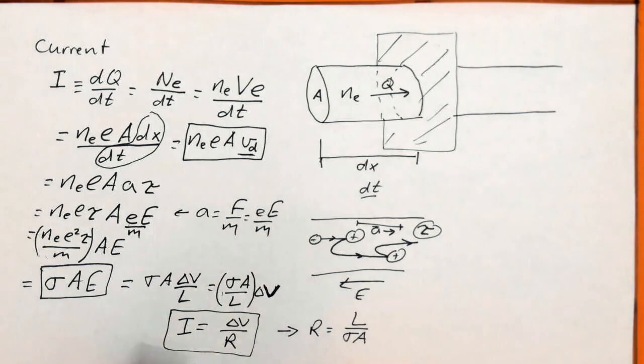And since sigma is conductivity, it's how well the material conducts. Since we're trying to talk about how much the object resists flow, we choose another parameter, which is simply 1 over sigma. So it really isn't anything new. It's just, if this is 10, then rho is 1 over 10. But this now is the resistivity. It's a material property, so silver has a certain resistivity. But now it seems to make more sense. Resistance grows with resistivity and grows with length, since there's more material to go through, and inversely with the area.